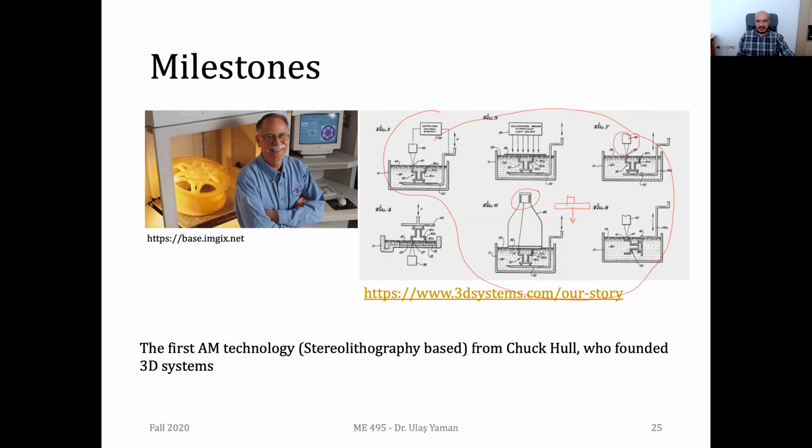We have liquid inside, as you see, but in this one, it's different. This time, the head is moving upwards after one layer is completed. And these days, the desktop versions of SLA systems or DLP systems are using this approach, which is much better than the other one, since in the other one, your part will always be inside the liquid resin. This results in some problems, so they switch to this approach. They are moving the table in positive Z direction.